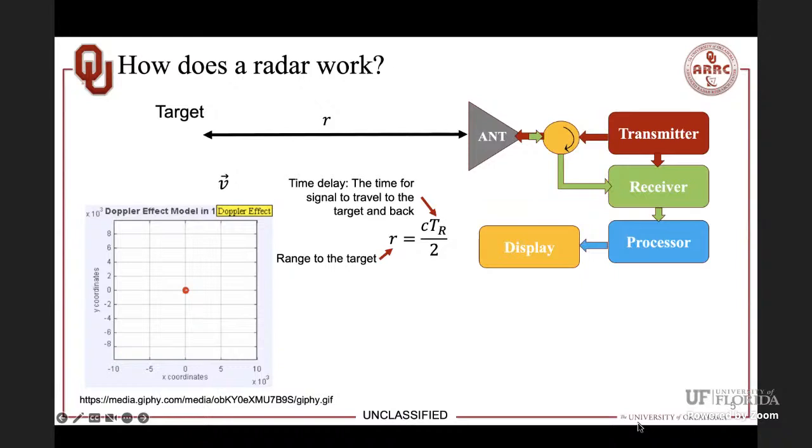So that time delay is the time for my clap to propagate from me to the wall and come back. Then this time, in this case, of course, times the speed of sound. But because there are two ways, the actual distance to the wall is half. So it's the same concept, but radar just uses electromagnetic waves. The key is that you need to make that clear. For radar, the way to do that is to send out a pulse, just like the bat. Send out that particular energy. It's not continuous, you just have that pulse.